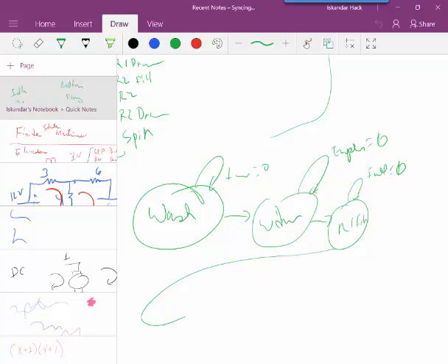You specify what inputs have to be high or low to do your state transitions, and you draw this huge bubble graph, and the software itself will then write the C code, or the VHDL or the Verilog. So going from the bubble graph to the code is fairly straightforward, and it can actually be done by software. You don't need a programmer anymore. All you need is somebody who's smart enough to draw the bubble graph. The programmer is completely irrelevant.